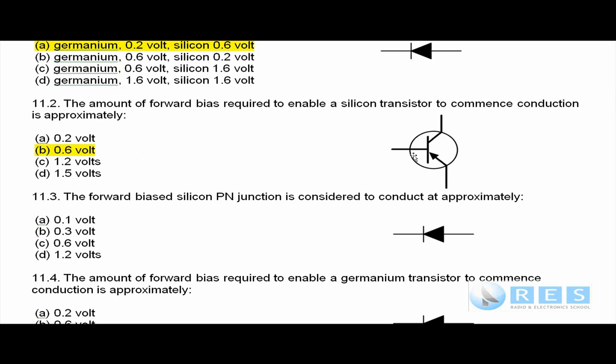I'll talk to you more about the transistor symbol later. Just for now, just remember that the base is the input, the collector is the output, and the emitter is common to input and output, and it is changes of base emitter current that produce a much larger emitter collector current. So if we change the base emitter current by 10 milliamps, we could change the emitter collector current by 100 milliamps, and that would be an amplification of 10. So a transistor is an amplifier.